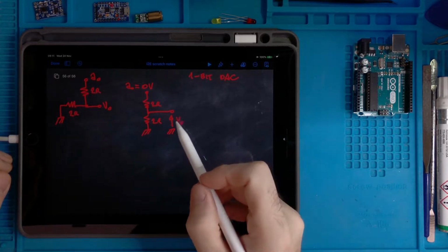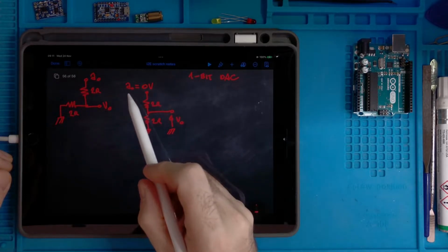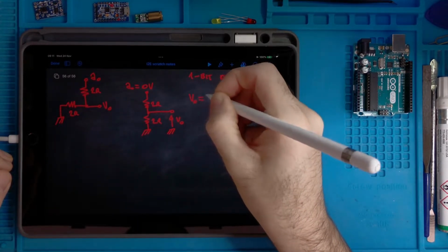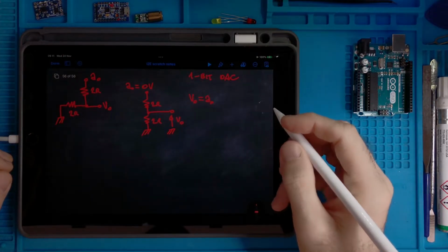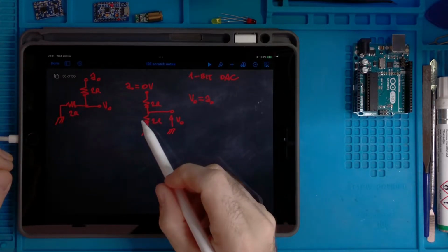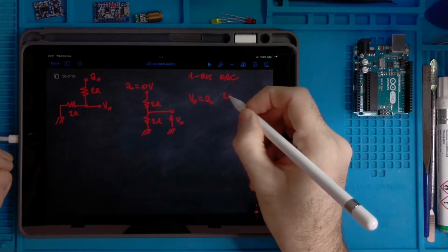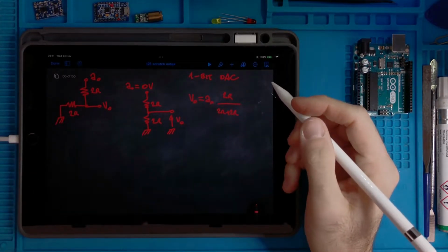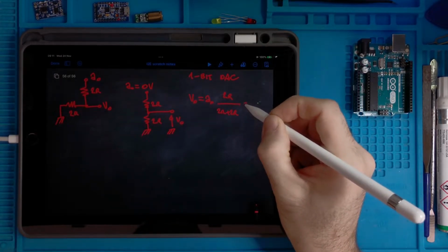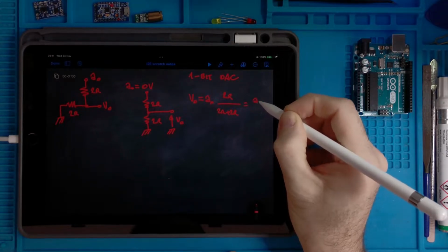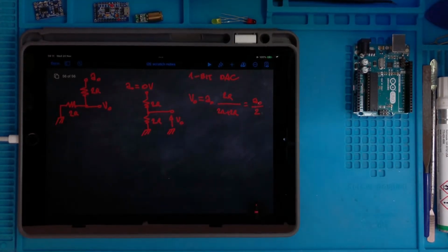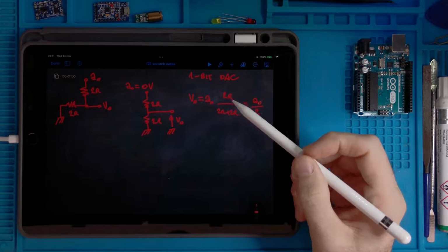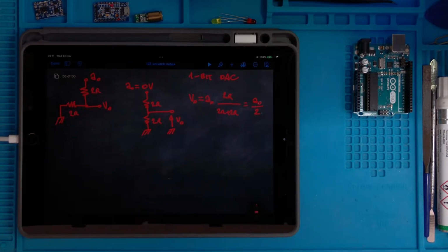So we can write the output of the circuit as a function of the input voltage for the given resistors. So the output voltage Vout is Vinput, we call it A0, multiplied by the resistor at the bottom, which is 2R, divided by the sum of the two, 2R plus 2R. And so this is A0 divided by 2, simply. So we cancel the 2, we cancel the R, and only this 1/2 factor remains.